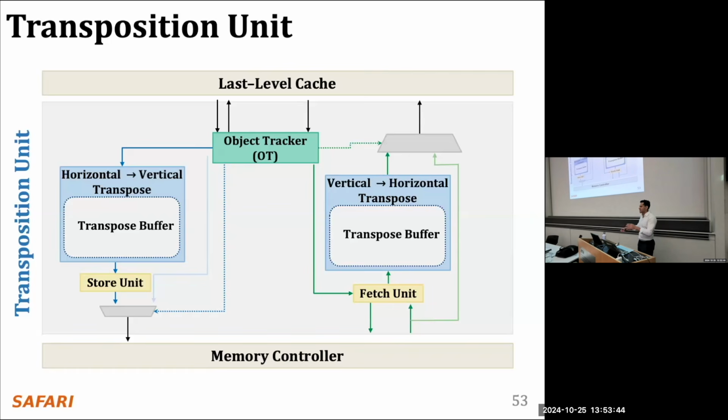And then the hope here is that while I'm moving on with my life, cache lines of the data were already evicted to the DRAM chip, so I can transpose that data without putting that latency in the critical path of the processing-using-DRAM operation, because it's going to be overlapped with, I don't know, you reading a file for something else in the application, for example.